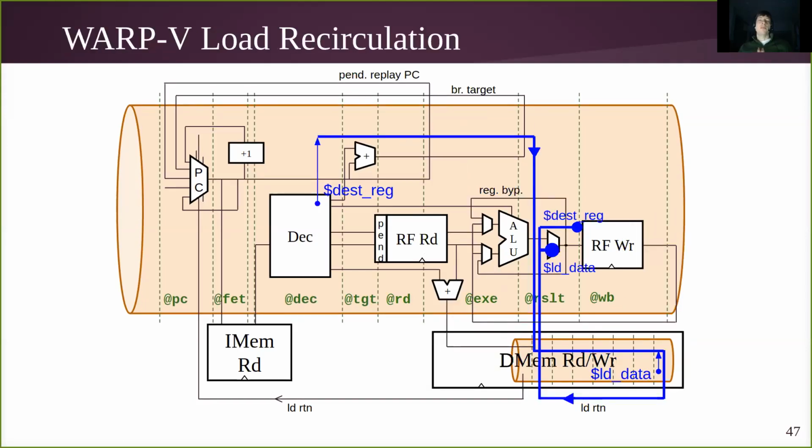So, focusing on the aspects of this model that are relevant to the verification problem. For the most part, the CPU pipeline is just a free-flowing pipeline, a very straightforward pipeline construct in TL-Verilog. Memory, however, WARP5 is written to support a variable latency memory access, and in fact, an out-of-order memory access.